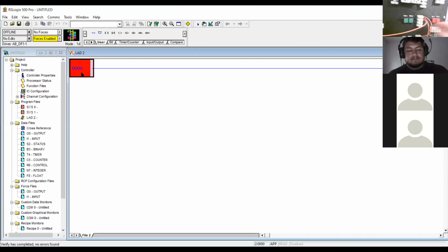So I've got power going into the top one from down here at the bottom. My power source, I've got it going up to the top of that button. I've got 120 volts going here. I've also got it jumping to the stop button, and then I leave the stop button here, and I'm going to input 0 that goes into the input section. And then the start button, I'm leaving it here, and I'm going to input 1.